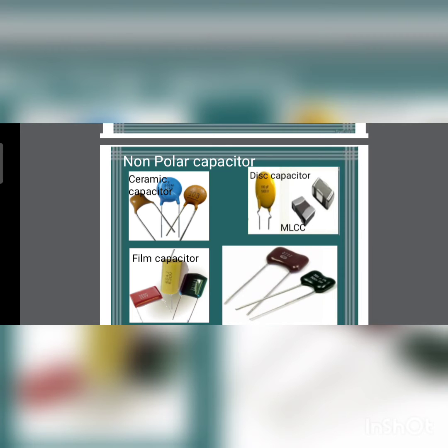Ceramic capacitors are available in different shapes and styles. That is ceramic disc shape, which is shown in another diagram, and MLCC. So the ceramic disc shape, which is the commonly used type of ceramic capacitor, has one layer of ceramic between electrodes, and MLCC, that is multi-layer ceramic chip, is rectangular shaped with multiple alternating layers of metal and ceramic materials.